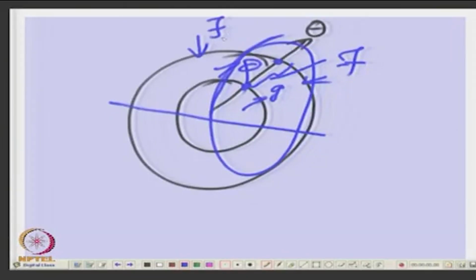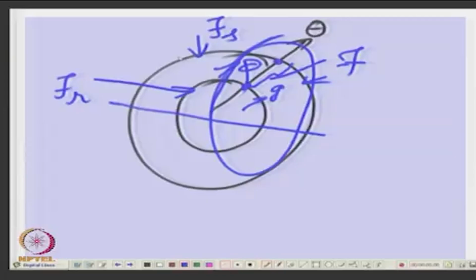Air gap flux is because you magnetize the stator surface and you magnetize the rotor surface, through putting conductors into the stator and into the rotor and passing currents in them. Then the difference between them will be the air gap flux.